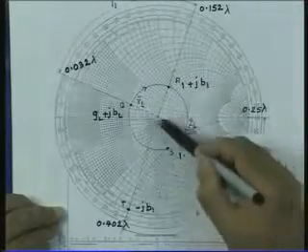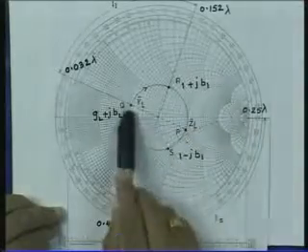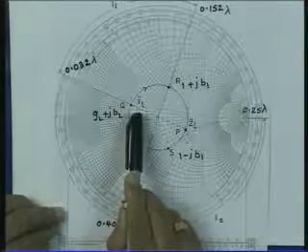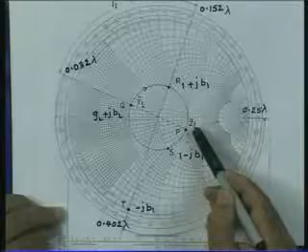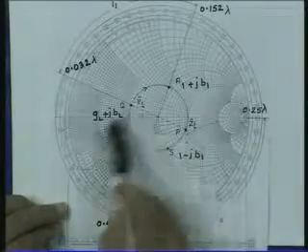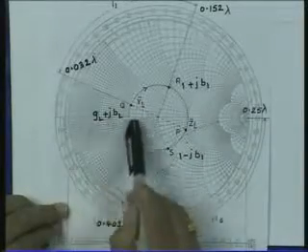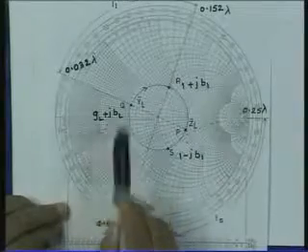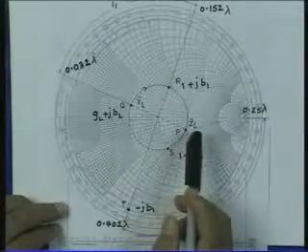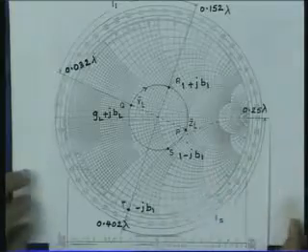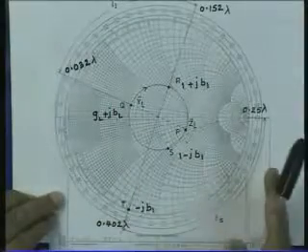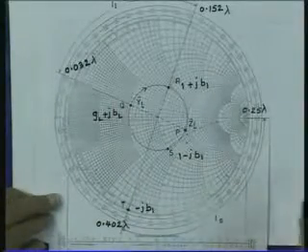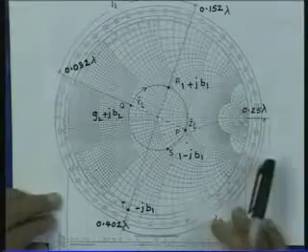So, this point, diagonally opposite point Q, gives me a normalized admittance corresponding to this normalized impedance. Let us say that normalized load admittance is GL plus jBL. So, essentially our single stub matching starts from here. This is the admittance which is to be matched by using a single stub matching, where stub is connected in parallel with the main line.